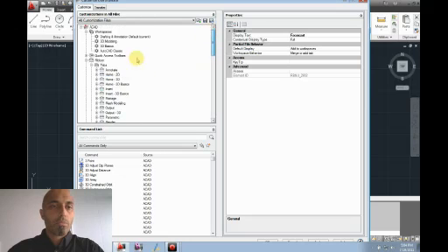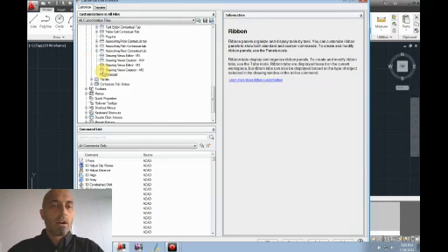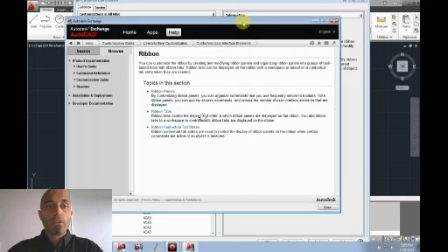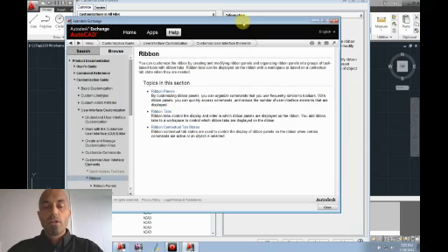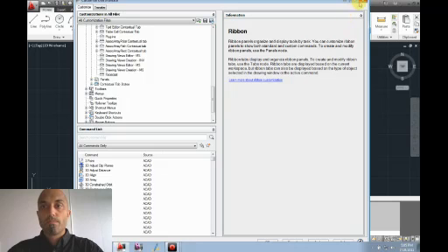Now I'm not going to go through too much and do that right now because it is quite a complicated area, but I definitely recommend coming into the CUI command, clicking on the help here, finding out more about how to make use of the concepts behind here: the ribbon panels, ribbon tabs, contextual states. You can get a lot of value from customizing your ribbon using the CUI editor.